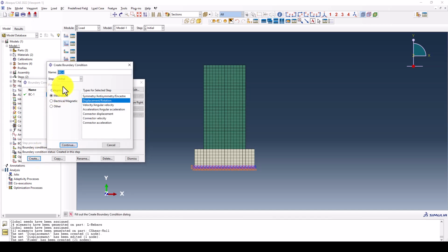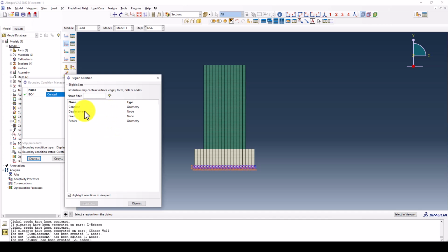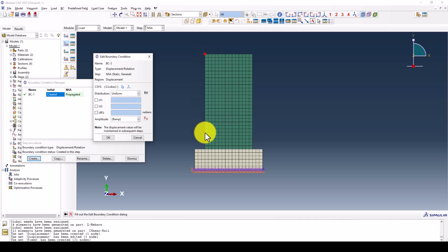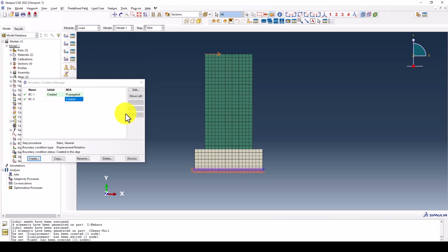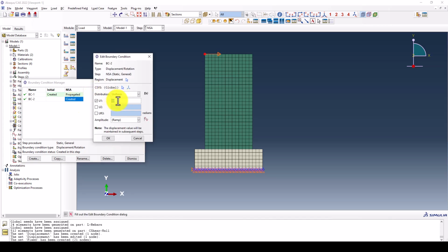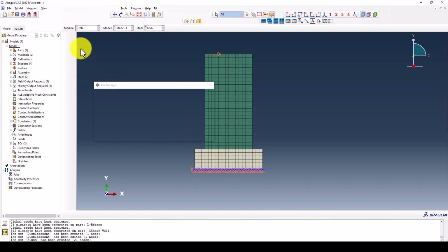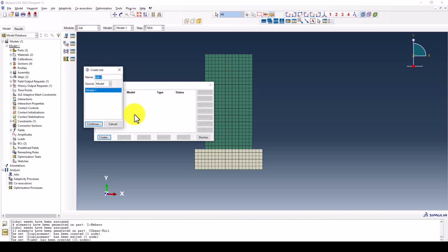And the last one is going to the nonlinear static analysis step. We're applying a displacement at this point. So for the displacement, the total height is 2.8 meters, so we want to take about 3%. So 0.3 times 2,800. This is 3% of the drift. So okay, if we see how much it is, 84 millimeters. So it's okay. Now we are done here, and we quickly go to the analysis. We just submit the job. We're going to call it pushover plane strip. Okay, plane strip.